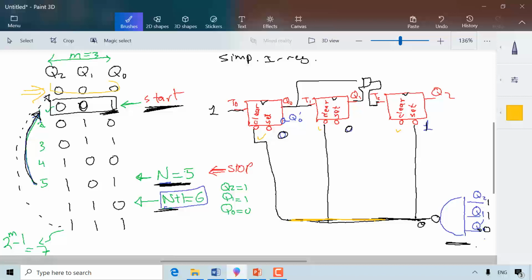All right. So what are the conditions under which I can use this solution? First of all, I must have a counter, and not any counter. The flip-flops must be equipped with set and clear inputs. You see how these have set and clear. Also, the counting sequence must be within one step. So in other words, I cannot do a random sequence.